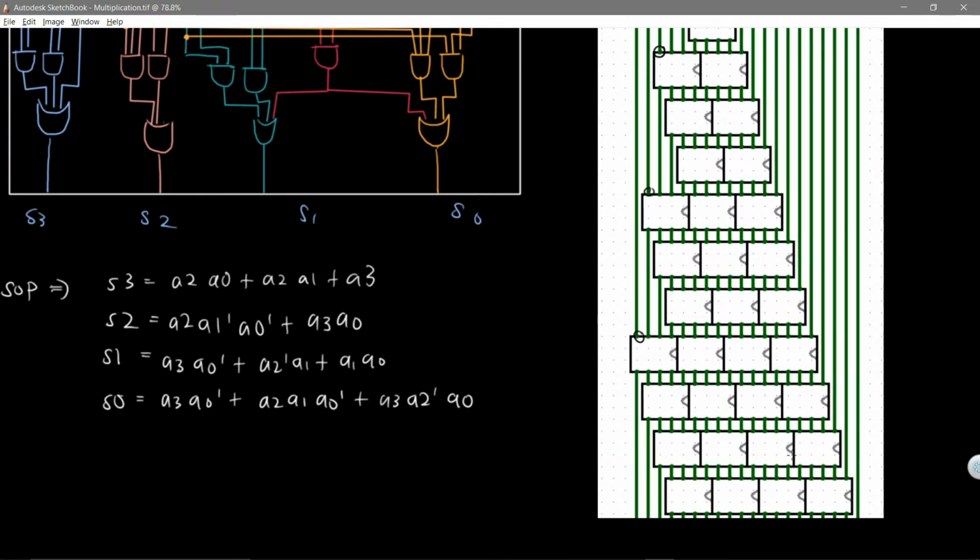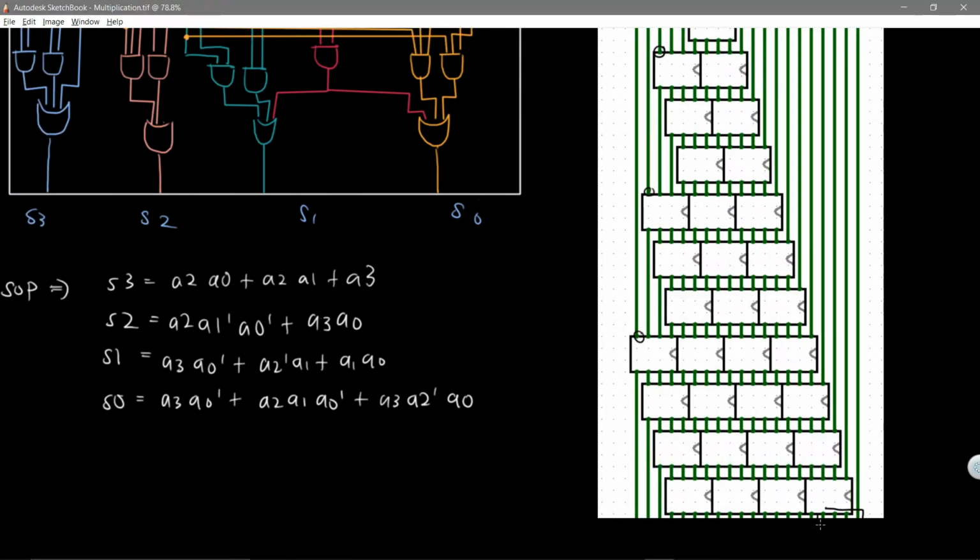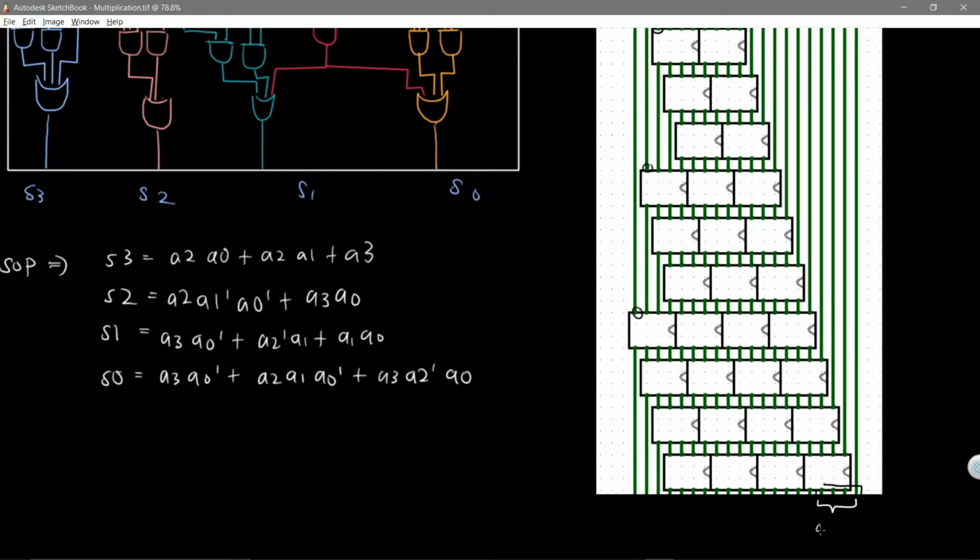So what a binary to BCD conversion does is, these 4 outputs are going to represent the ones. These 4 outputs are going to represent the tens. These 4 outputs are going to represent the hundreds. It's arranged in this way because a binary coded decimal only goes from this here to this here, so you only need 4 outputs, right? That's the nature of the codes.